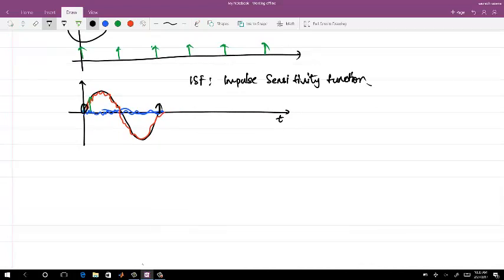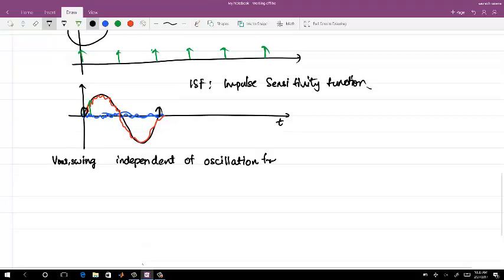Okay. So what we want to do is we want to have V out swing independent of oscillation frequency, or maybe directly proportional. One way you can always say I can amplify this oscillation amplitude with some amplifiers and always maintain the same amplitude. But if you are going to do that, that particular block itself will add the noise. So right now we are looking for having a same output swing independent of the oscillation frequency.